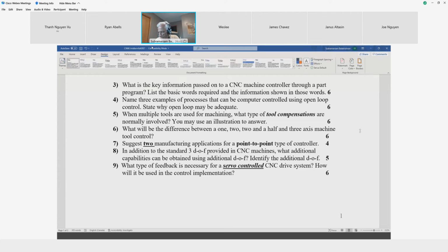Like what you did, the 4 holes being drilled on the housing, it just goes from one point to another point in the air. There is no interpolation, nothing, as rapidly as possible, and then dips down. That's the point to point. Okay, thank you.